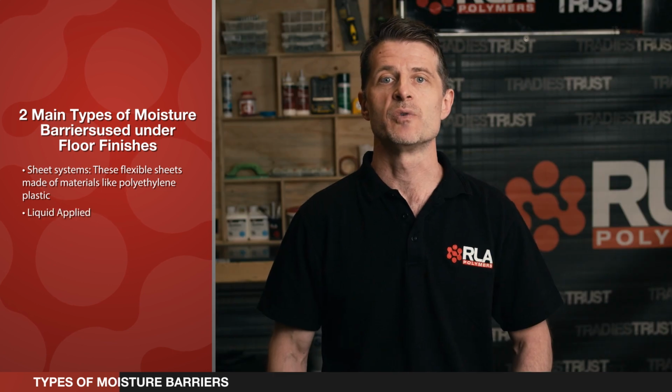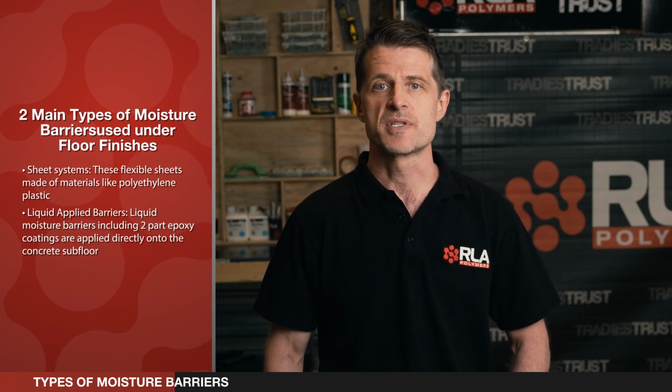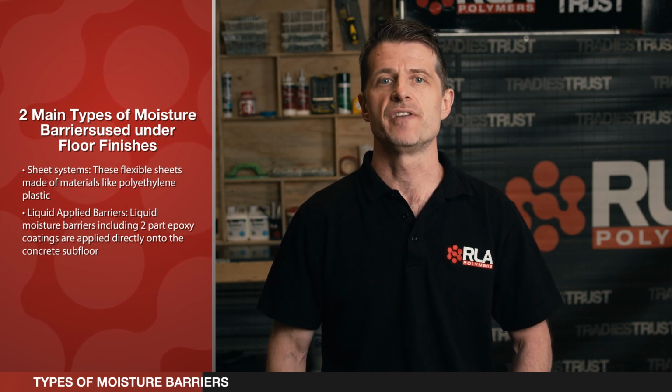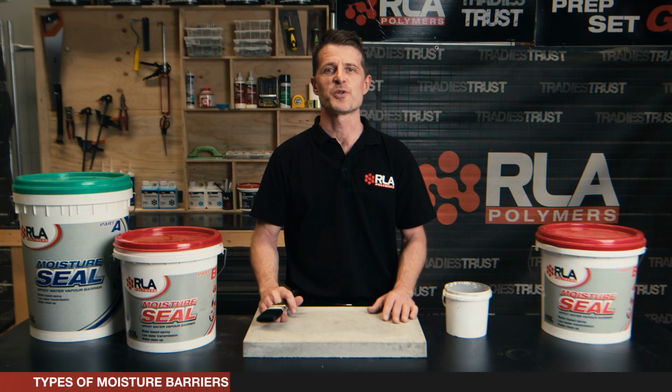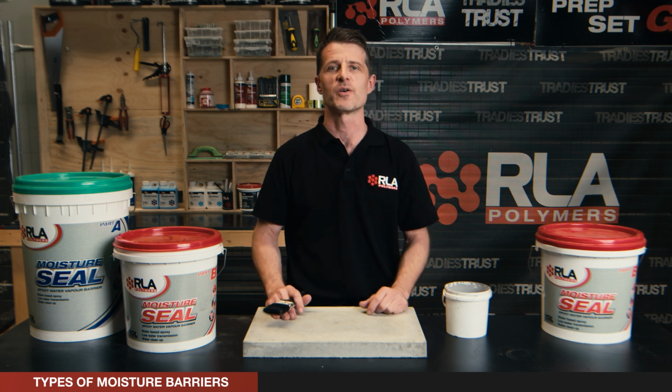And the second is liquid barriers. Liquid moisture barriers include two-part epoxy coatings and are applied directly onto concrete subfloor. They create a continuous seamless seal against moisture and are used for floor types that are typically adhesive fixed to the substrate, including timber and vinyl. So we've looked at the two different types of moisture barriers, the sheets and liquids. Here, we're going to concentrate on the liquid moisture barrier varieties.